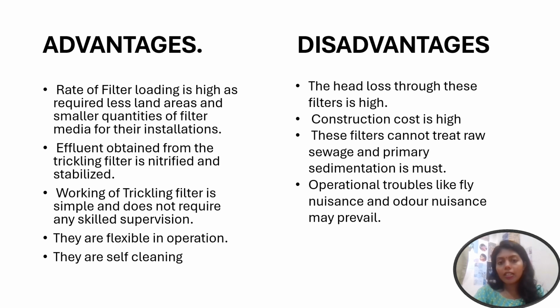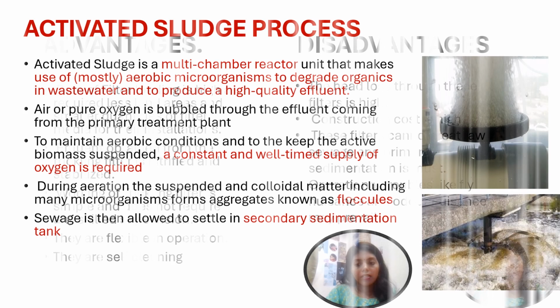They are self-cleaning. And coming to the disadvantages, the main thing is that the primary cost and construction cost are very high. These filters cannot treat raw sewage, and primary sedimentation is very important before doing this process. And operation troubles like fly nuisance and odor nuisance may prevail.